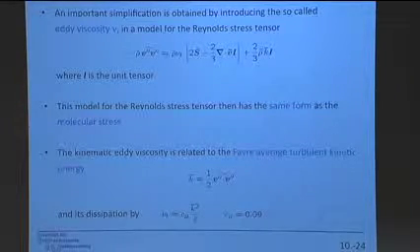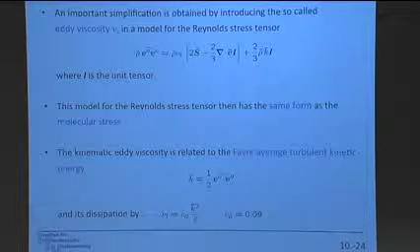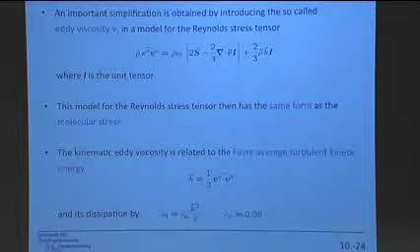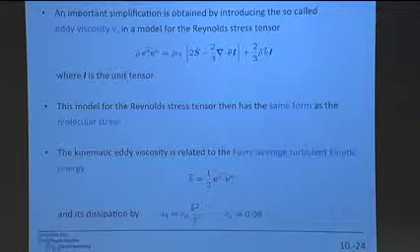You see there's a tensor here, we say v double prime dot v double prime, that's a scalar. And one half of that is the kinetic energy of these fluctuations. We call this k, the turbulent kinetic energy. And that is the most important characteristic of turbulence, kinetic energy. And then this is my velocity scale already.